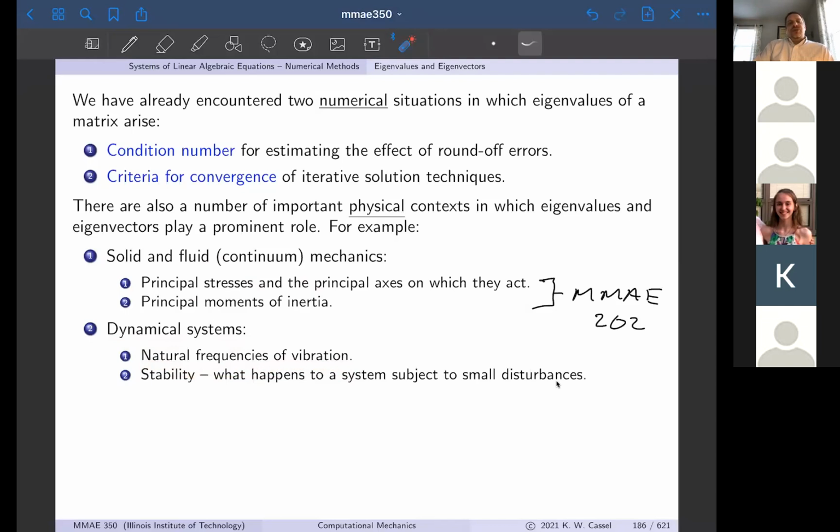That was a case where a resonant frequency was incited by the wind passing by the bridge structure, which caused large amplitude vibrations and eventually a collapse. So natural frequency of vibrations is a very prominent, very important example for us as engineers.